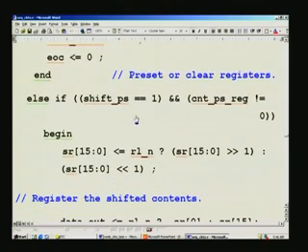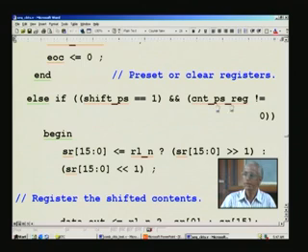Here we want to shift only if this signal goes high, and also we should have that counter non-zero, indicating some more bits are waiting for transmission. But if it becomes 0, we stop the transmission. For this condition we naturally have to do the shifting and output the result as such. So, this is basically a mux to do that job based upon the right or left signal.